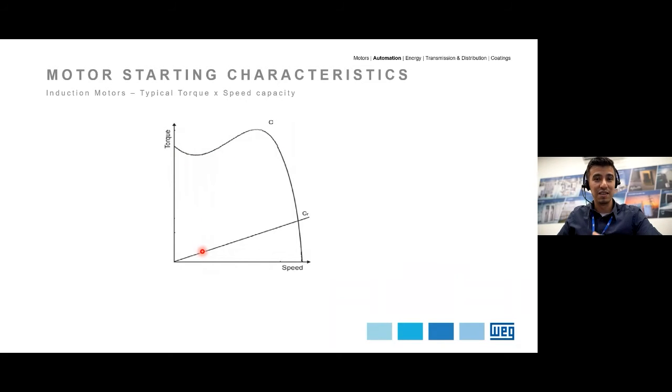Because your motor torque is higher, you can accelerate and spin this application, up to a point, which is this blue dot you can see in the graph. At that specific point, if you go any further, your resistive torque will be higher than what your motor has to give, so you won't accelerate any further than that, right?